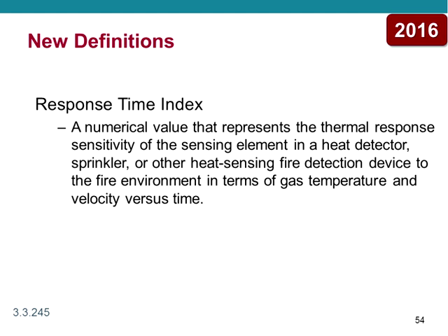We did add a new definition for response time index, and the reason we did this is because we talk about heat detectors in elevator hoistways or machine rooms used for elevator shutdown. And when we talk about those heat detectors, we say that they must have a lower response time index and a lower temperature setting than the sprinkler that they're located within 24 inches from.